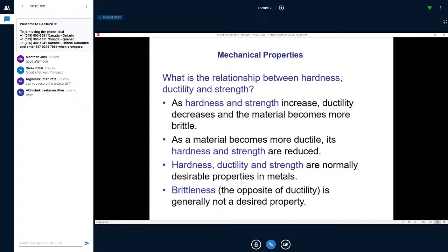If you want really high strength and high hardness, you're going to have brittle parts, and you may have to have whoever is using that equipment that has that very hard and strong part pay more attention, or replace the part before you expect it will fail.